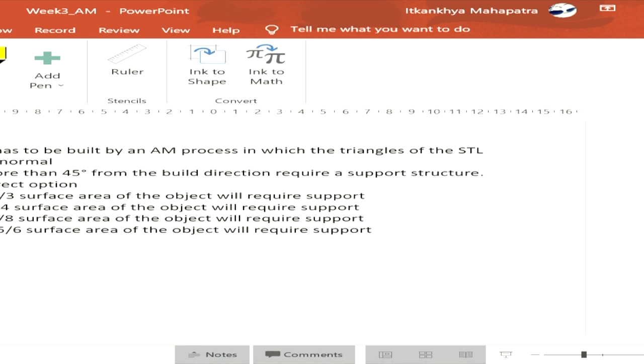Now here, a sphere has to be built by an additive manufacturing process in which the triangles of the STL file whose facet normals are at an angle more than 45 degrees from the build direction require a support structure. Now select the correct option. More than 2/3 surface area of the object will require support, less than 1/4 surface area will require support, less than 1/8, or more than 5/6. Now we will understand the question and solve it.